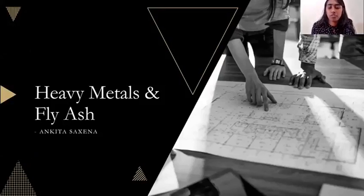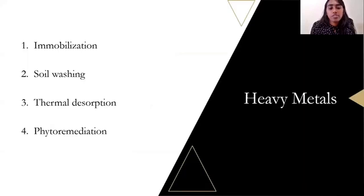Heavy metals such as lead, mercury, and arsenic were found in the soil. The first method is immobilization. The immobilization strategies are used to prevent heavy metals from leaching into the environment by enhancing physical characteristics of the soil, reducing the surface area across which pollutants can transfer. Immobilization can also be achieved with the help of biochar, which is an emerging technology. Next method is soil washing.